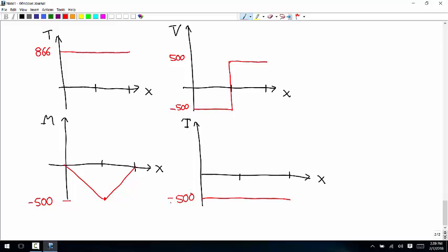What these three tell you is that no matter where you are, the internal loads are about the same. Here they switch signs, but that doesn't change anything. This is just as bad for it as this is, and vice versa. The only thing that has a preferred location, places where it's less likely to break and more likely to break, is the bending moment.